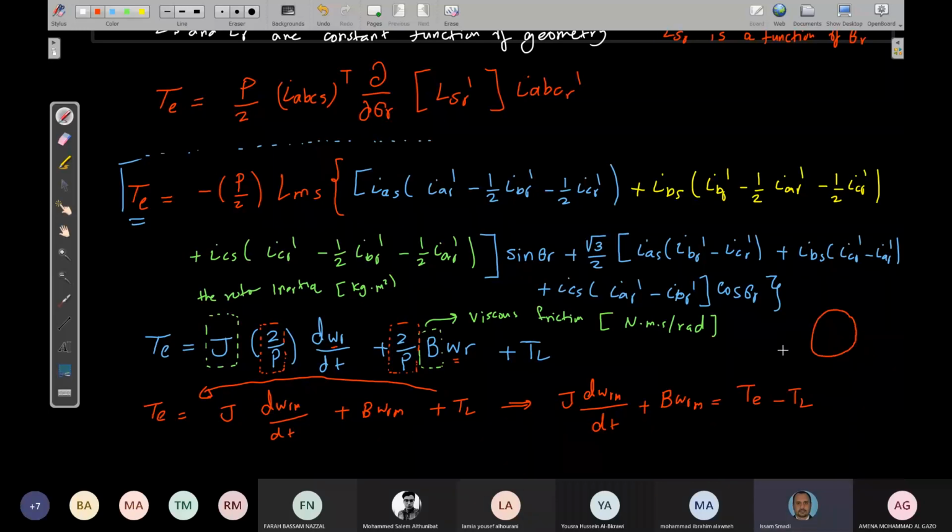The electrical speed is something else: how many times the flux changes its polarity, let's say north, south, north, south. How many poles do I have here? 4 poles. So this means the electrical speed is twice faster than the mechanical speed.